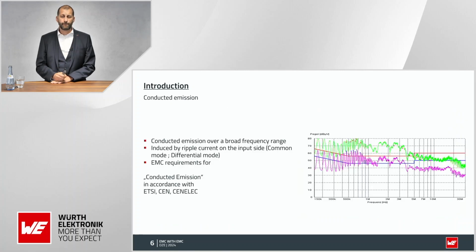Superb. Well, I already talked about thresholds, and we have a range where we have to measure. In this case, if we speak about conducted emission, it's currently 150 kilohertz up to 30 megahertz. This will change in the future. We will probably have to go lower than 150 kilohertz. Why in this range at all? Because in this range, most of the noise is going to stay on the cable.